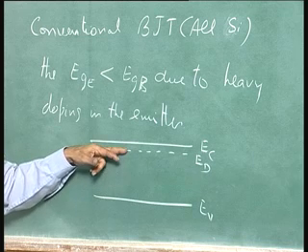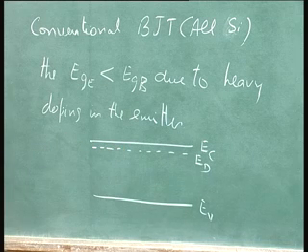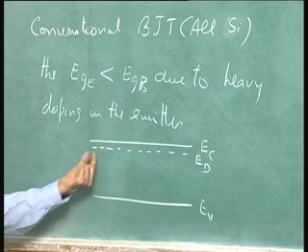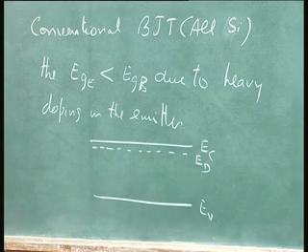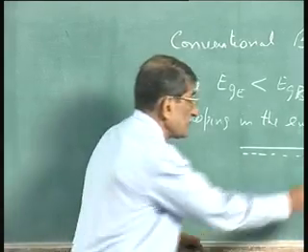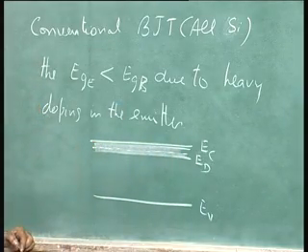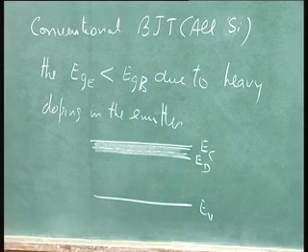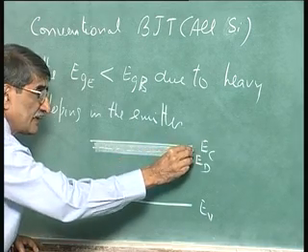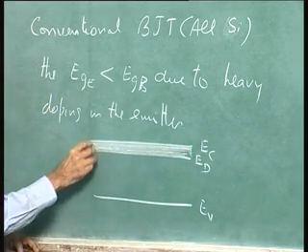Now, if you increase the donor concentration to like 10^19, 10^20 in the emitter or 10^21, what happens is each of these levels will interact with each other. So, what is one level splits up into a band. So, you get an impurity level like this, band like this, and once the concentration goes something like 10^19 or upper 10^18, this is a donor band.